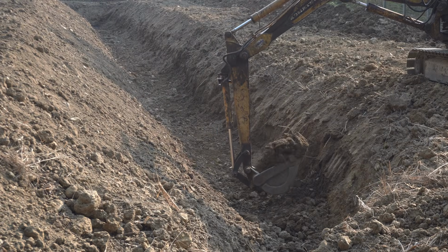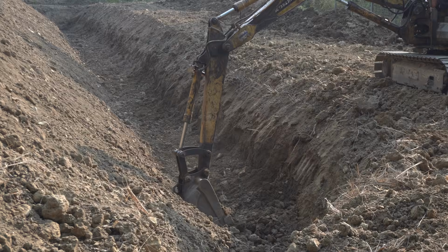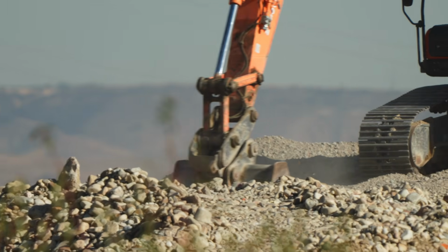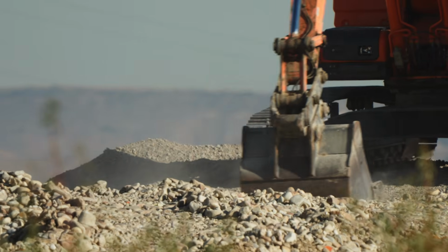For example, if we have to do 1,000 meters of trenching at $50 a meter, then it's going to cost $50,000. If we have to do 2,000 meters, it's going to cost $200,000. I just proved I can't do maths in my head while talking to the camera. It's actually going to cost $100,000. But at the end of the day, the relationship is simple. The quantity of work derives our direct costs, and the other important relationship to understand is that the quantity of work also drives how long the project takes, which drives our indirect costs.